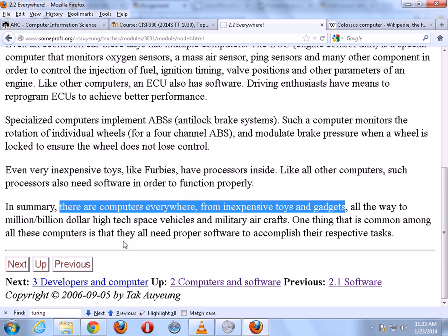What would be the next revision of this technology? Bluetooth, right? You use your phone, you pair it with your torque wrench, and then you go through an app on your phone. You can specify the torque. Now, you don't even have to specify the torque, depending on the application, because you can select the vehicle based on make and model year, and the app already has the preset for it.